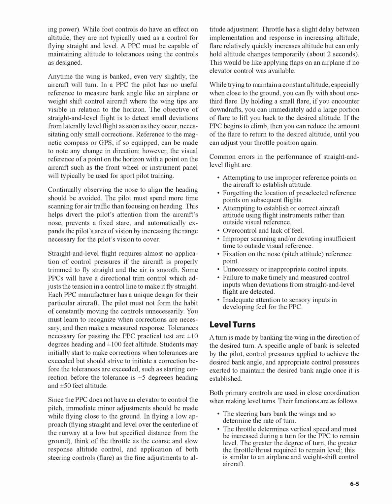Anytime the wing is banked, even very slightly, the aircraft will turn. In a PPC, the pilot has no useful reference to measure bank angle like an airplane or weight shift control aircraft where the wing tips are visible in relation to the horizon. The objective of straight and level flight is to detect small deviations from laterally level flight as soon as they occur, necessitating only small corrections. Reference to the magnetic compass or GPS, if so equipped, can be made to note any change in direction.